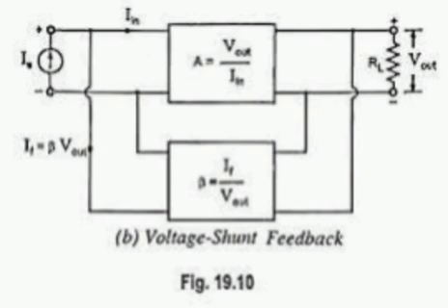Common drain amplifier. Voltage gain AV equals mu RS in the numerator, denominator rd plus (mu plus 1) into RS, which equals V0 by Vi. If small rd tends to infinity, then AV equals GM RS, that is the numerator part, by 1 plus GM RS, that is the denominator part.